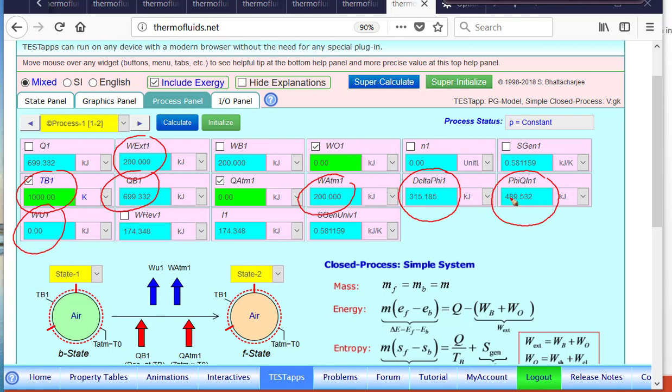The ratio of the two is called exergetic efficiency, or sometimes second law efficiency. This is the Exergy that entered the system, and this is the Exergy that was stored, and no Exergy came out as useful work. Therefore, the difference must be what is known as irreversibility.